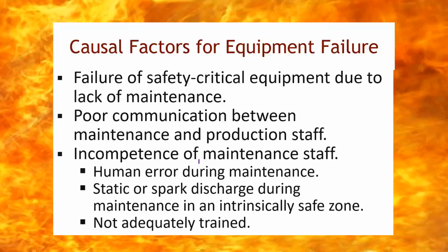There's some issues related to that, new OSHA requirements. If you do have a process that's being brought in, it has to be a third party or a qualified engineer who has to study what the hazard level is related to the fumes or air contaminants that could be flammable or explosive. And they have to document the demarcation of that.